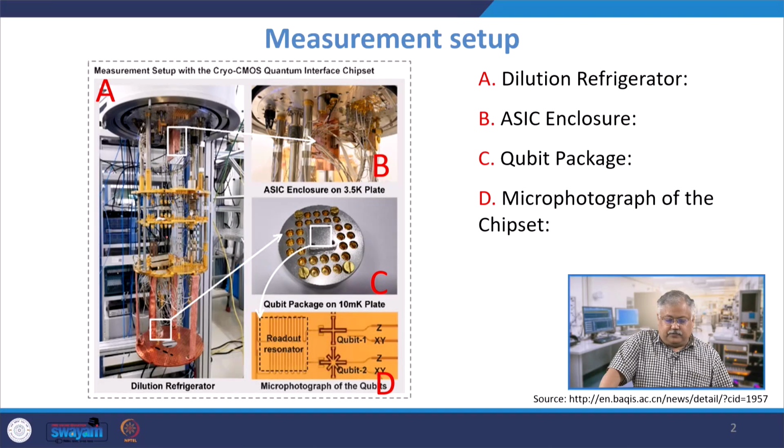We will start from where we left again in the previous lecture, and this was the measurement setup which is there. Please understand, the cryogenic fluids will be flowing within this chamber here. So there is a small chamber here, right, at the bottom here, which stores basically the qubit package. The qubit package, which should be kept approximately at around 10 millikelvin, is placed somewhere in this package, right? And this is actually sort of vacuum packed inside an enclosure, across which you will have interconnects running for controlling the qubits as well as reading out from the qubits.